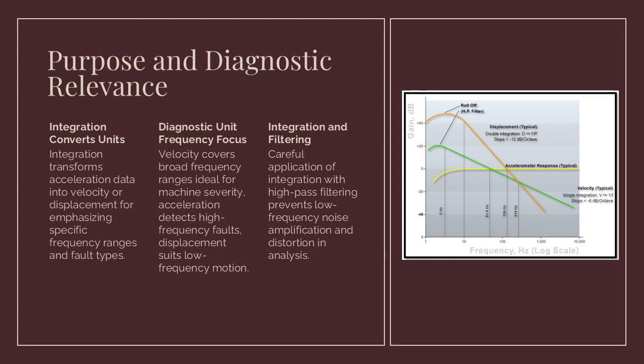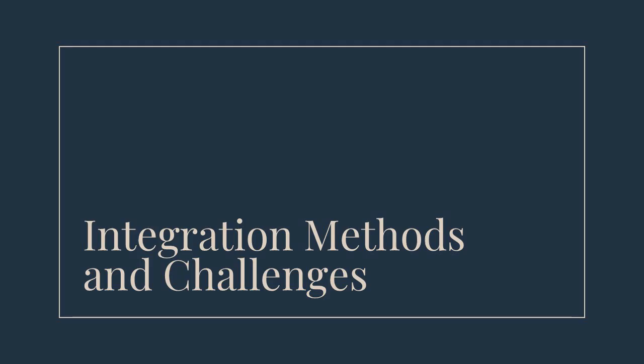However, integration must be applied carefully, as it can introduce errors if low-frequency components are amplified excessively. This is why high-pass filtering is often combined with integration to suppress unwanted low-frequency noise and prevent distortion in the velocity or displacement spectrum.